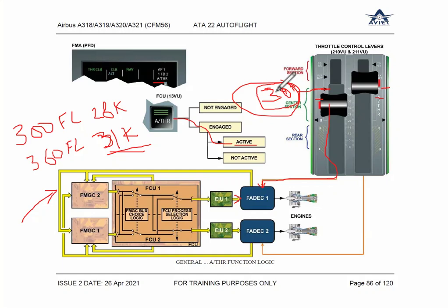Are you getting me, guys? Yes. So the thrust lever plays a very important role even in auto thrust condition. So let's say your lever was here before a high angle of attack. Auto thrust is applied, the thrust goes up to TOGA automatically, correct?